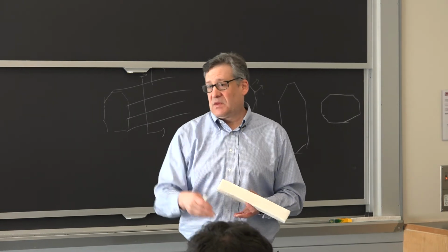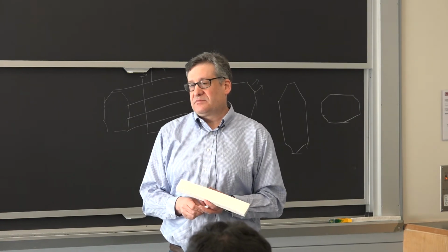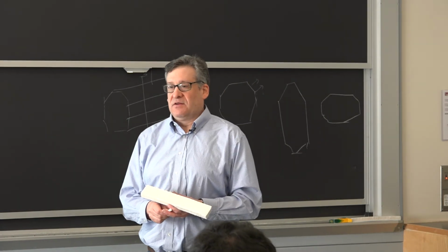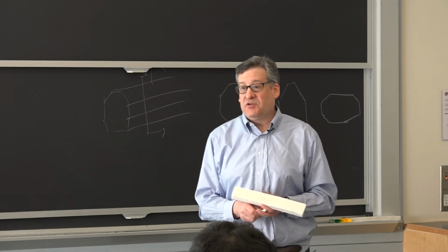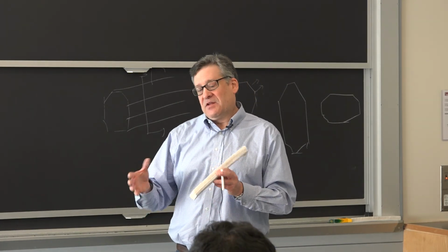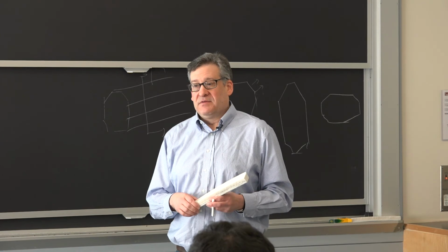Does shape optimization assume a constant cross section, or does it change it along the way? You can put those constraints in. You can tell it a constant cross section. You can put in draft angles for a stamping, for example, to make sure you can get it out of the die. That's the neat thing about it. You can tune it to do whatever you want it to do.